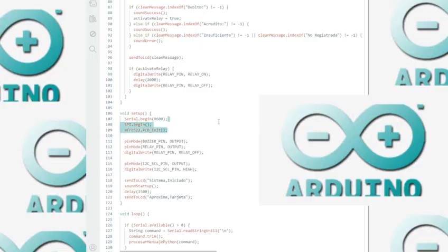The functions initialize the SPI hardware and send configuration commands to the MFRC522 to activate the antenna. Software I2C configuration. Here we simply configure the SCL pin as output and set it high. We send a welcome message to the LCD and execute the startup sound sequence.